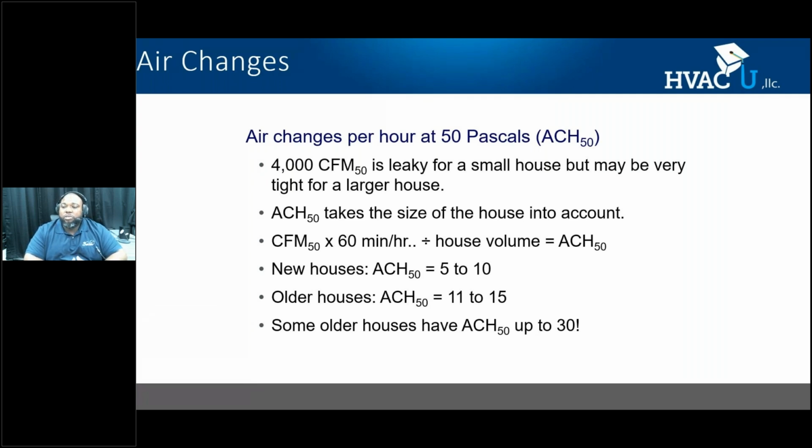All right. Some houses are so leaky that we have to use a blower door, maybe with multiple fans, just to get it up to 50 pascals test pressure. So you're talking about some serious leakage. Without doing a blower door test, you won't know what your air leakage is, and it will be a pure guess if you describe it by something other than the actual leakage rate.